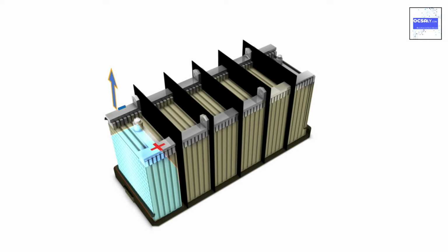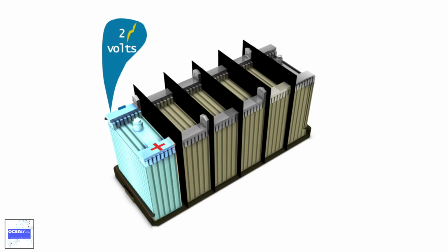This refers to the time taken in minutes for a battery to discharge to a cell voltage of 1.75 volts when supplying a constant current of 25 amperes. This test reflects a typical current drain for a vehicle that will be needed if the charging system failed during night driving. The reserve capacity of a 40 ampere-hour battery will be approximately 60 minutes.